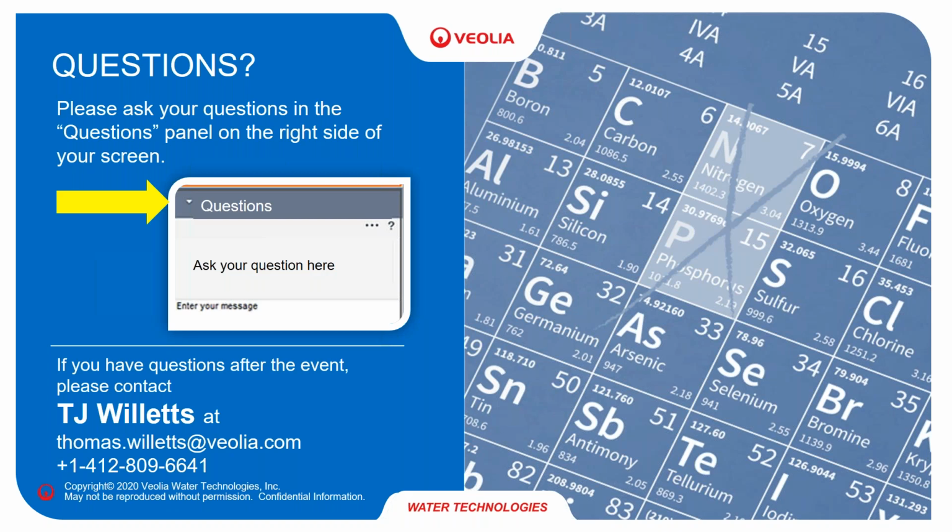Everything that I can remove biologically, I will not be paying for in cost of chemicals. So if I come in at 150, I know I can remove 30-40% biologically, and the rest will still need to be removed using chemistry. I will most probably fit economically with a return cost of less than a year and a half on operational expenses. I would fit in biological phosphorus removal pretty nicely.